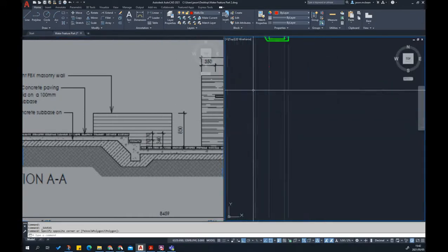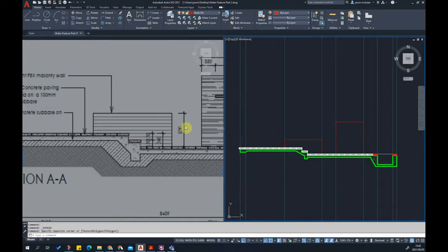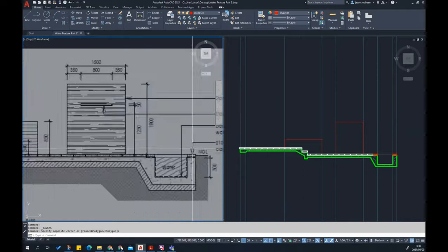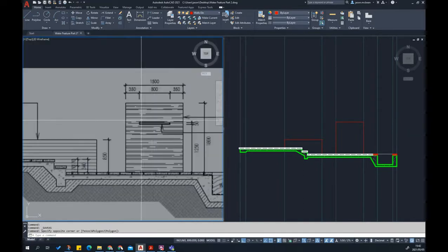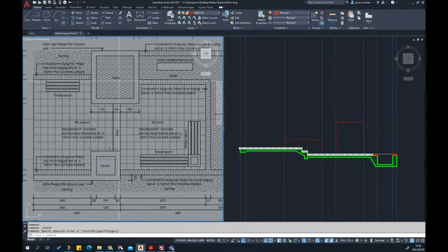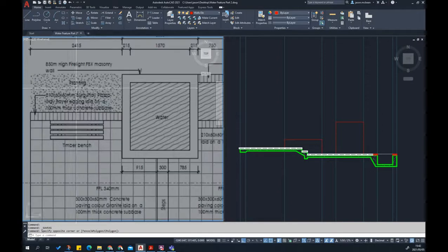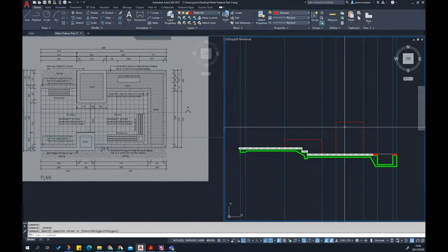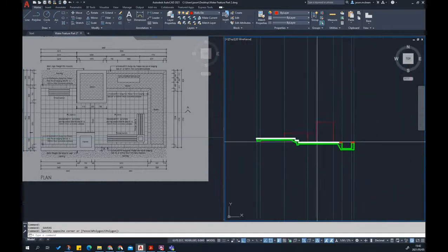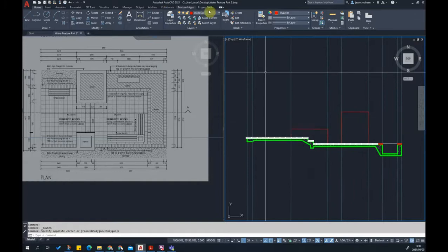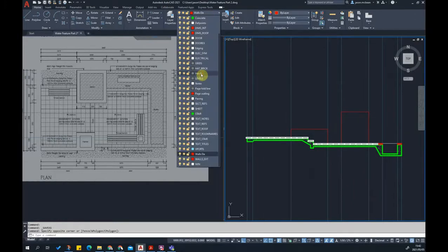But I think the first thing we need to focus on is just using hatches correctly, and start looking at how we would fill, so how they would probably fill this up a bit better, making this little stainless steel detail, using like a stone detail hatch over here, using a water hatch over here, okay, those kind of things. Okay, adding some planting, adding this edging, for example. Okay, so the first thing I'm going to do on this elevation over here is focus on using some good hatch work. Okay, so hatch, enable hatch.